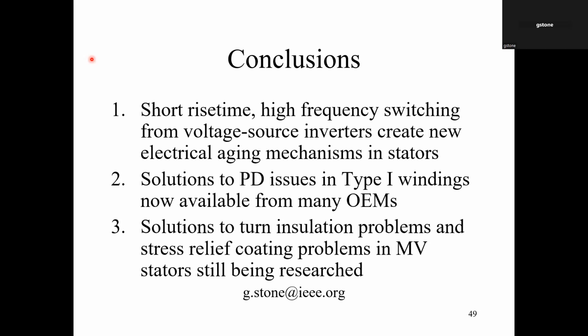And what I've seen, and of course this is just what I've seen, is that in the early days, especially the lower voltage motors, they just used what's called a dip and bake process, where they dip the whole stator in a tank of warm varnish, and they hope that it would impregnate it, and then they put it in an oven to cure it in place. But the reality is it doesn't get rid of all the voids.